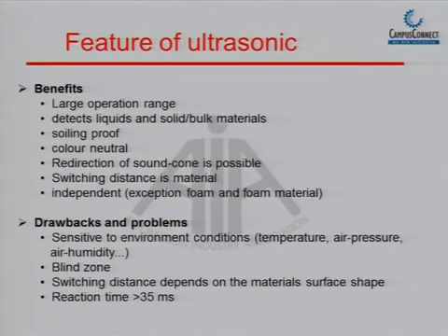If you talk about inductive, we can only go up to a certain distance, not beyond a certain limit, that is more than 100 mm. If we talk about capacitive sensors, again 50 mm, 60 mm is the maximum sensing distance that we can get. In ultrasonic sensors, we can go up to a larger distance, the distance can go up to a few meters. Then again it is not dependent upon the type of target,